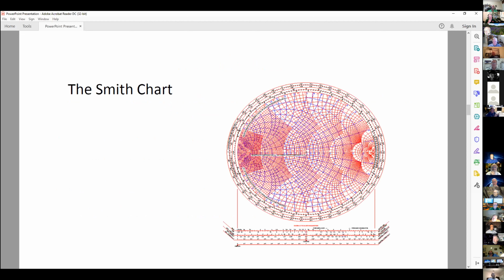which I will go into in a little, I think I'll just go ahead and go into it, but around the circumference of the chart is the length of the transmission line, both to the load and away from the load. Down here on the bottom are these straight lines called radial parameters, where you drop a line down from the graph straight onto this, and you can read things like SWR, reflection coefficient, loss factors, any of those parameters. So that's the Smith chart.